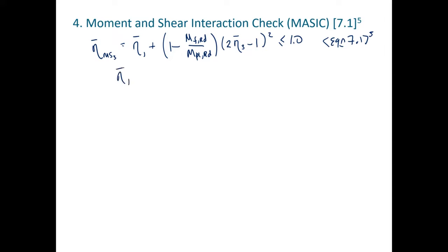Okay, so what are all these? So the first utilization ratio is just the demand divided by the capacity for the panel that we're looking at. So it's 5,115, and the capacity is 5708. So 5708 came from step 2.